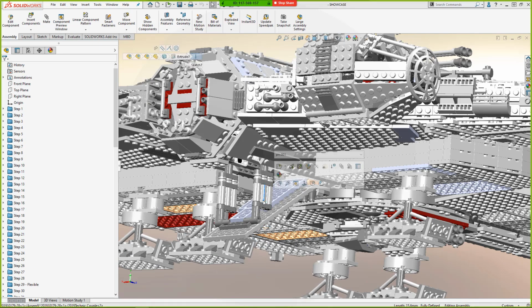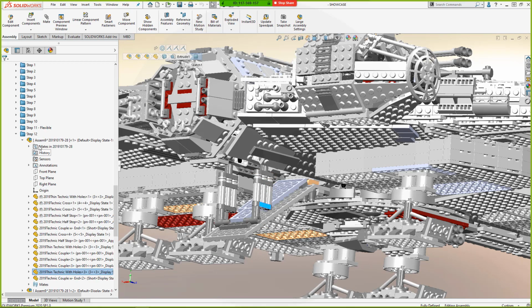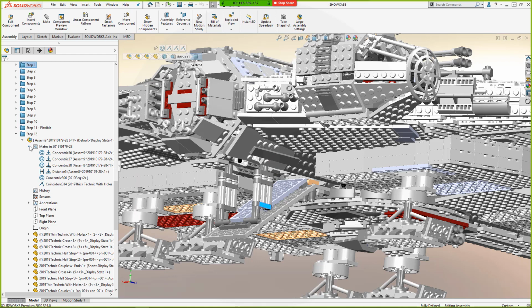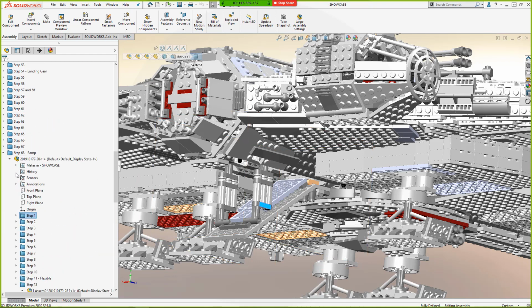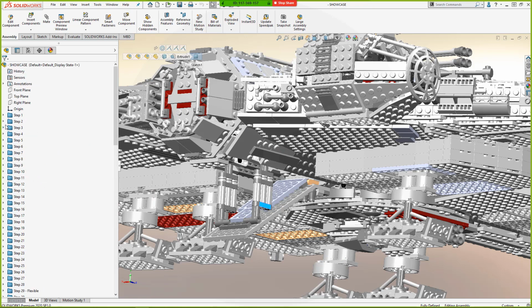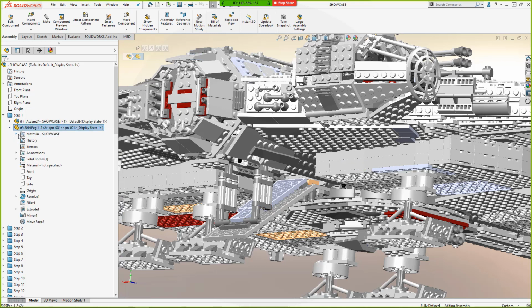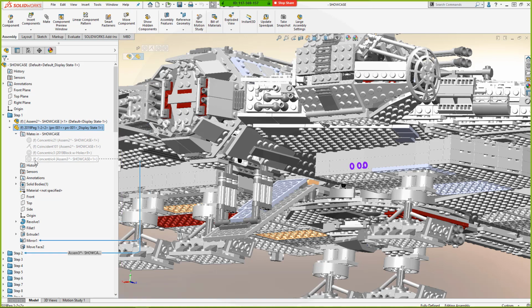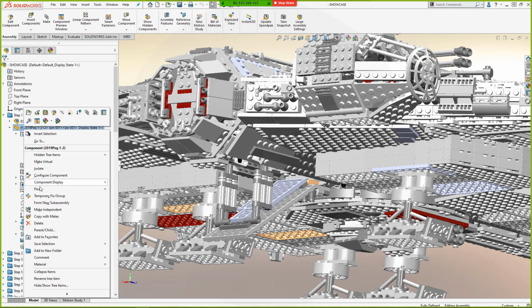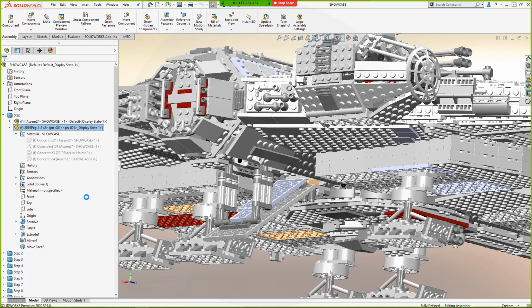So we've got a number of subassemblies in here, and we can see that one's got the mates already. I may have left a bunch of these already unsuppressed. Here we go. Just to demonstrate, when we have this fixed in place, you can see the fix because we've got the F there, and it shows that all of the mates are now not being resolved. If I choose to float that in this configuration, for example, it's going to recalculate all of these mates at that time.